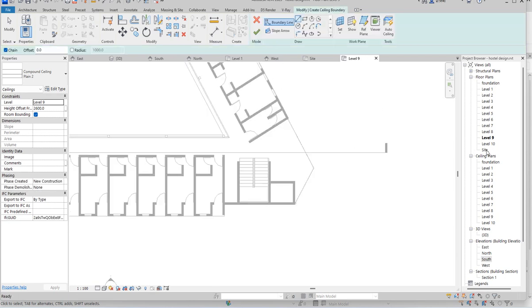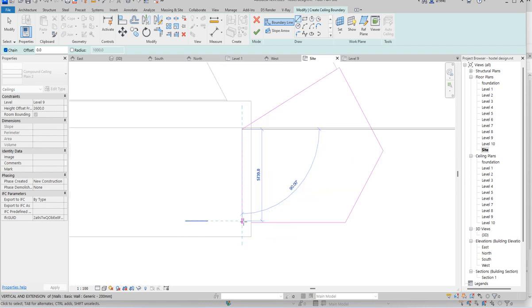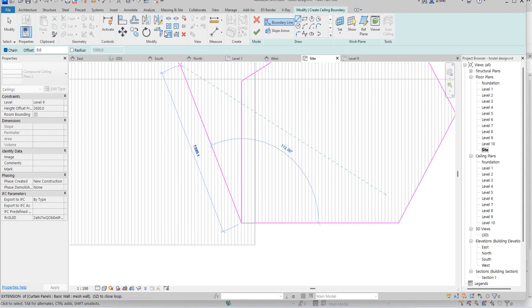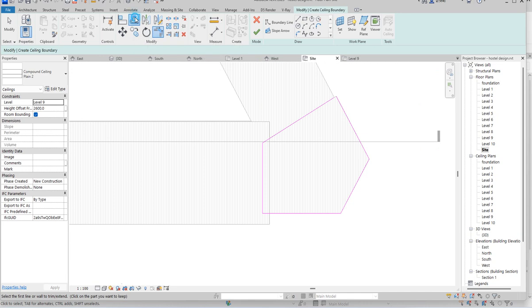So I will go to level, site level, and I will follow the procedure properly. So I will say click using the line. You get now. So I will use this line to do that which I need to do. Then I will connect this together. So connect that together, and I will say click OK. Now for this one, having this, what I need to do is to offset this one by a little bit. Let me just say 100 or 75 will be okay. 75 offset inward without copy.